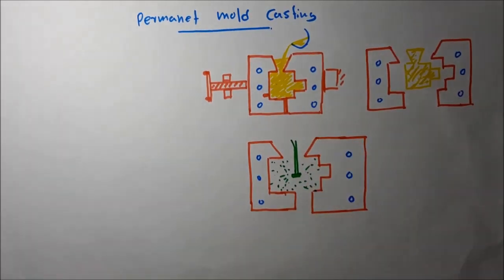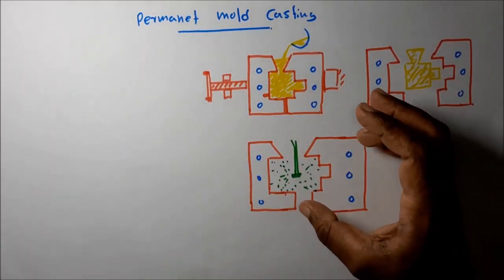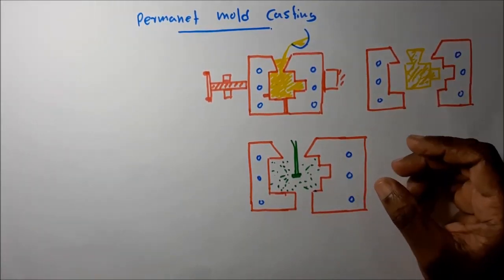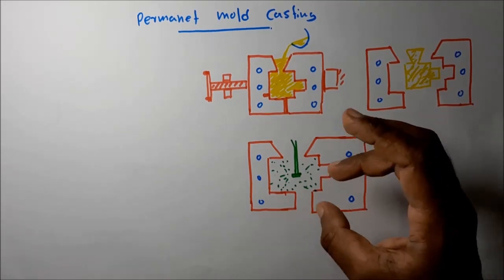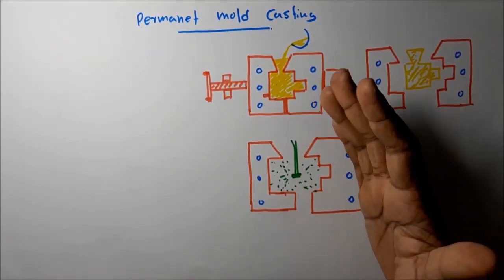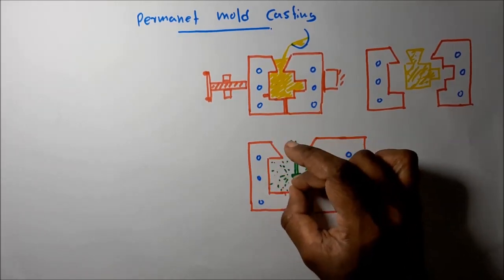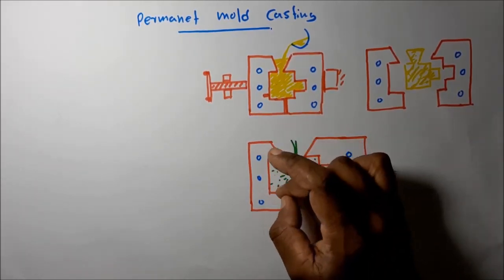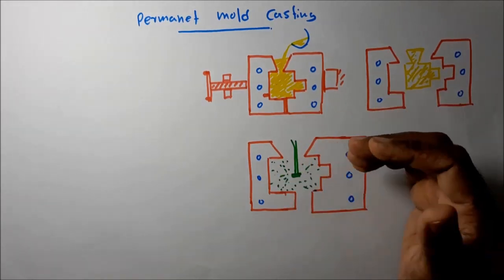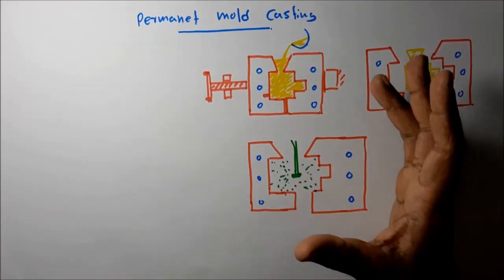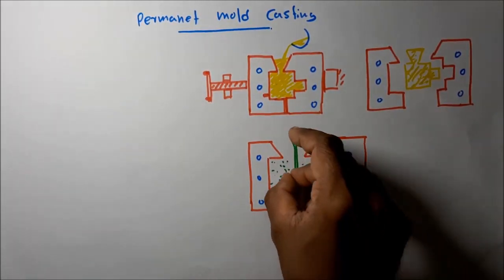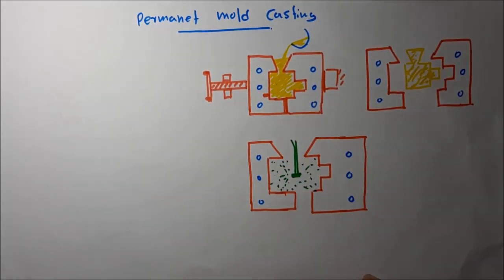It enhances the fluidity of the molten metal throughout the mold, and it enhances the release of the part easily after it solidifies. It also acts as thermal insulation, avoiding immediate solidification during the pouring. That is why these graphite lubricants are applied.